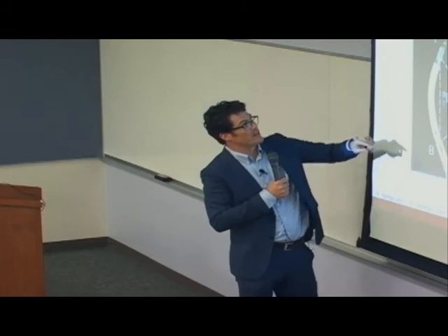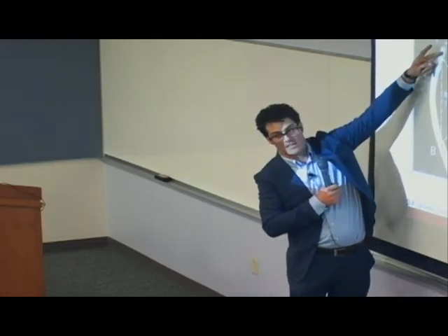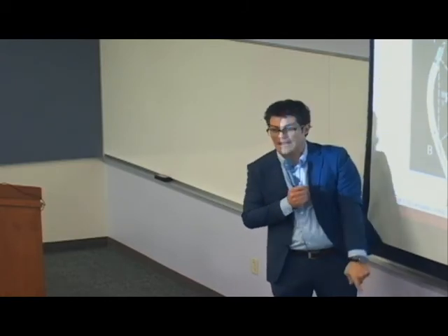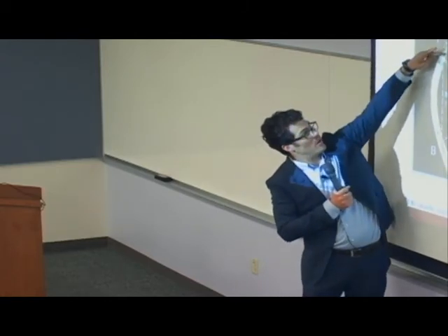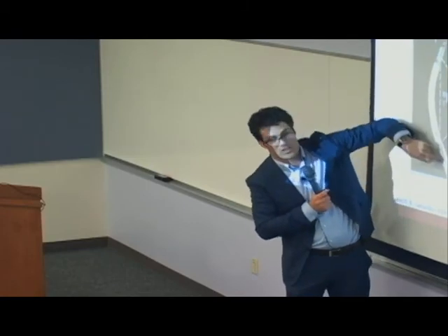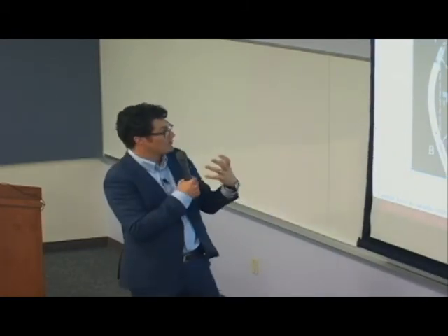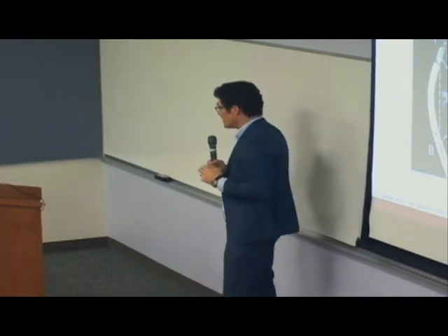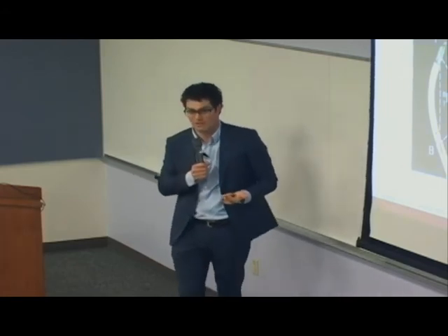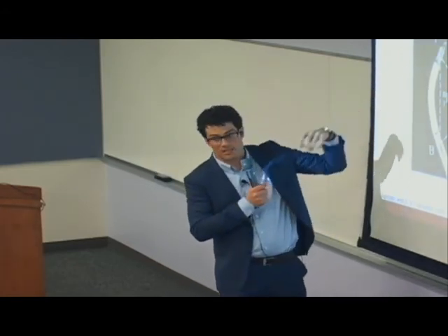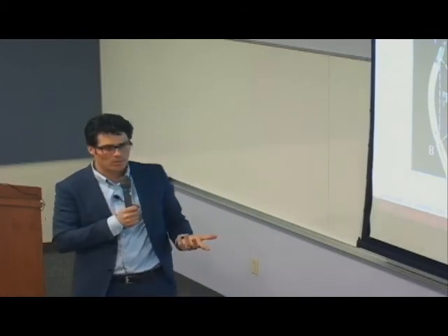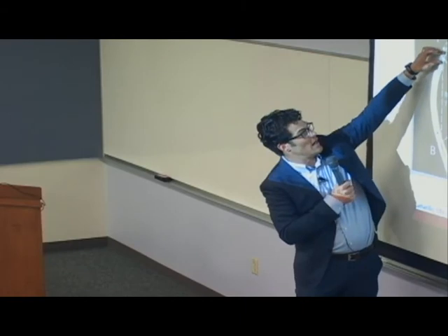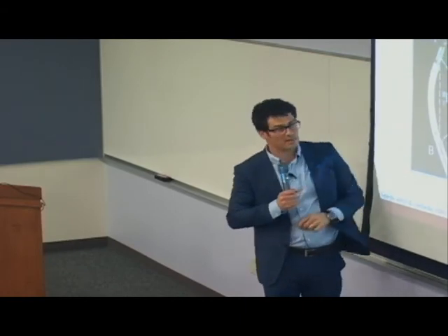And so the idea here is that if we have a sensor on the tip, so this tells you the Cartesian position, orientation in this case as well, and you know the tendon displacements, then you can figure out this relative rotation, and that allows you to then globally figure out where your device is in space. Now, this is very simple to do if you have a 6-dimensional sensor, and if you have an electromagnetic sensor, which the bronchoscope that we're working with does. All you're doing is essentially a rotation matrix from here back to here.